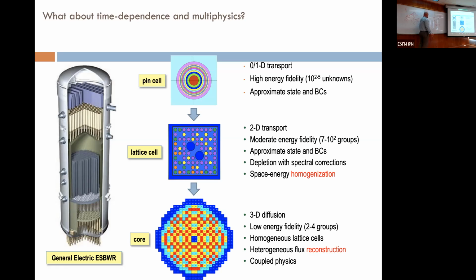And so your Courant limit is saying you want no more than 50% of the fluid from this cell to go into this cell to try to slow it down. And so the smaller your mesh size, the smaller your time step size is. If you have mesh cells that are on the order of 20 centimeters, you can have big time steps. If your mesh cells get down to 1 centimeter, you have to have smaller time steps. If you do Reynolds-averaged Navier-Stokes, it gets even smaller.